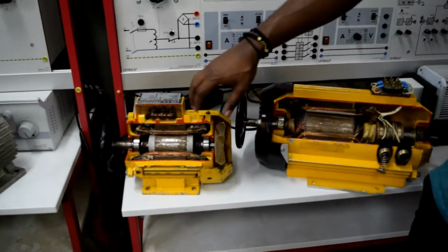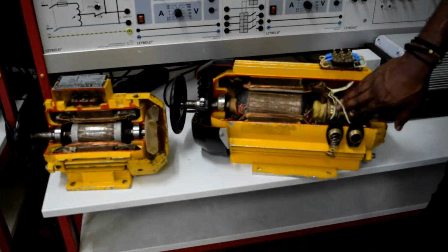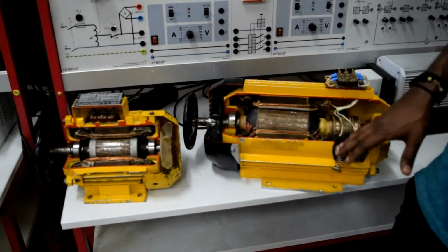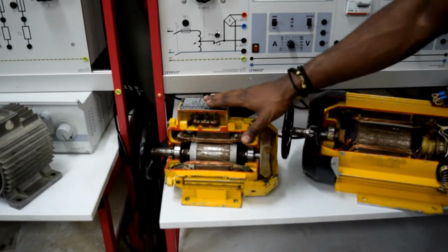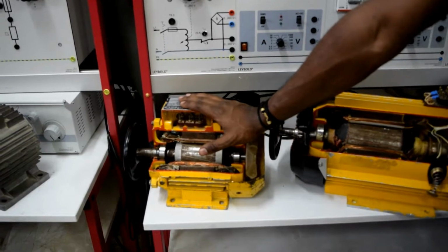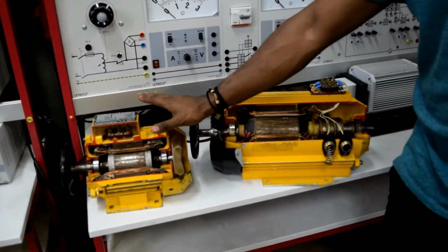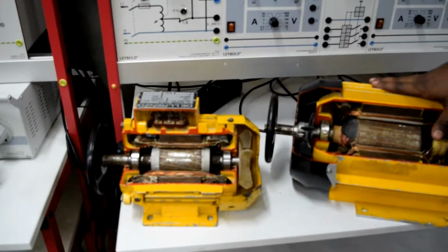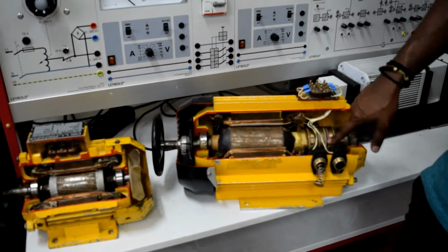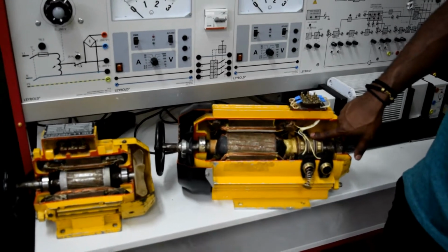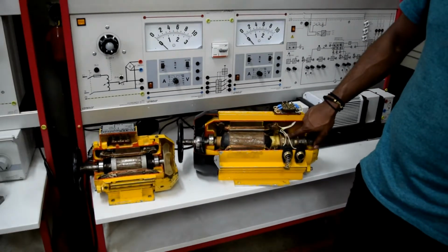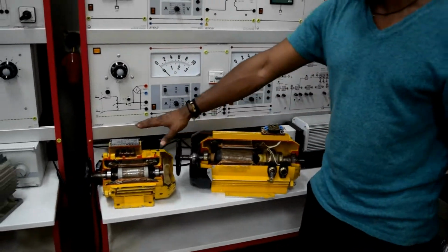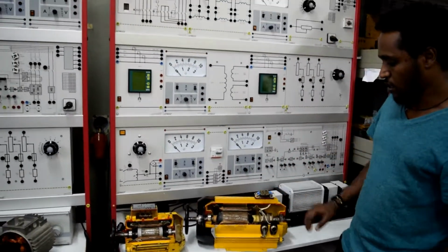But because of the cost, when we see here, we have a cost for slip ring and brushes, so the cost is more than the squirrel-cage one. The squirrel-cage is rigid in construction, so most of the industries use squirrel-cage one rather than phase wound, because we have additional cost and we also have losses due to the phase wound. So because of that, we choose squirrel-cage mostly rather than a phase wound one.